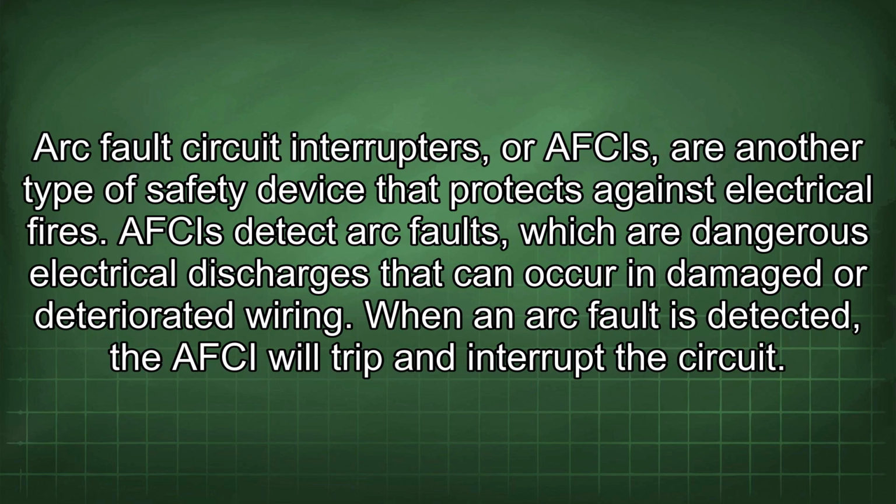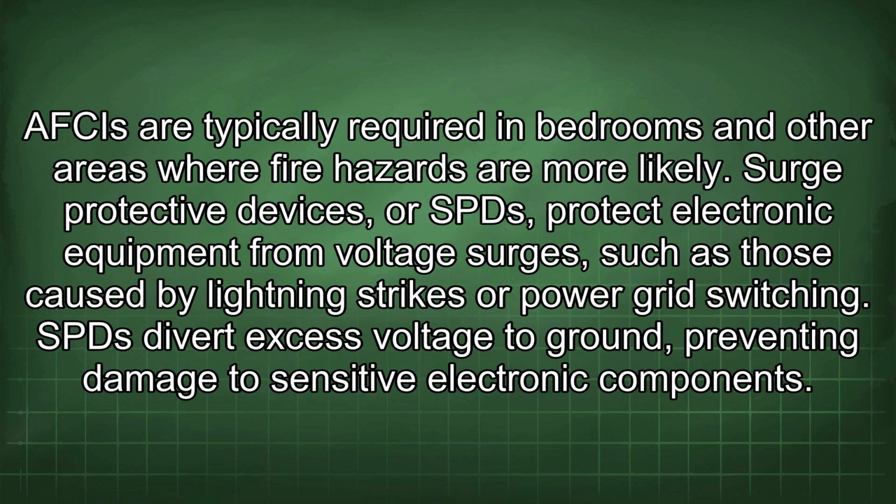Arc fault circuit interrupters, or AFCIs, are another type of safety device that protects against electrical fires. AFCIs detect arc faults, which are dangerous electrical discharges that can occur in damaged or deteriorated wiring. When an arc fault is detected, the AFCI will trip and interrupt the circuit. AFCIs are typically required in bedrooms and other areas where fire hazards are more likely.